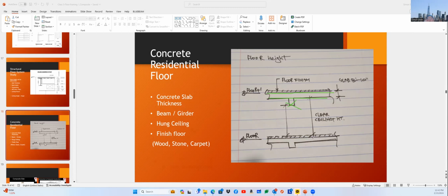Because also their ceiling height requirement is relatively lower than office, because your space is smaller than office. So your ceiling requirement is slightly lower. But obviously, for the structural system of residential buildings, we mostly use concrete. So do not mention that you designed a concrete building for your office building. It's a wrong statement, right? Because at least I want you to understand the basics of the basics. In the United States construction industry, concrete is mostly residential, steel for commercial.